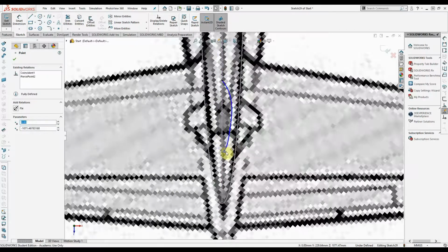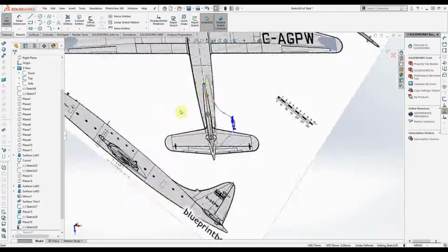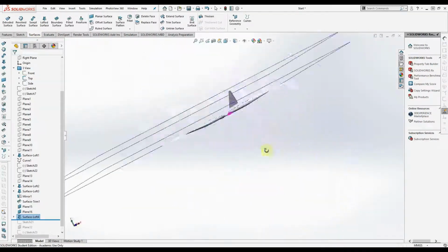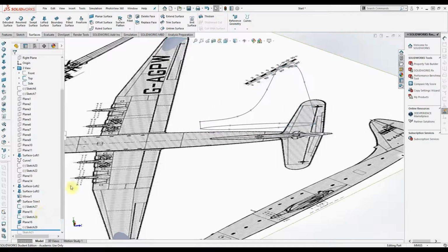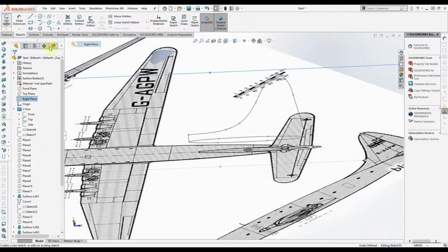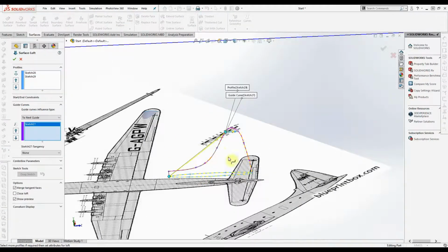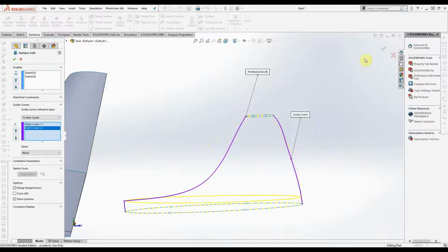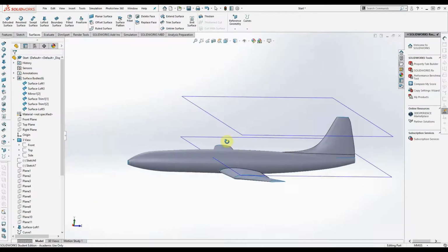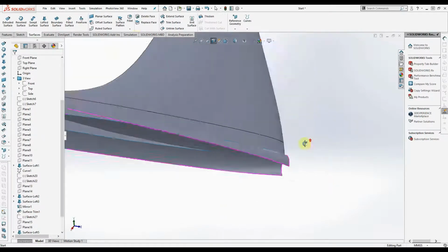And again, draw the same sort of shape, coincident it or pierce it with the reference sketch, make it look somewhat nice. And then I'm using the reference sketches to guide the loft to what I need. Here I'm having problems just because the reference sketch is not fully coincidented with the bottom plane.